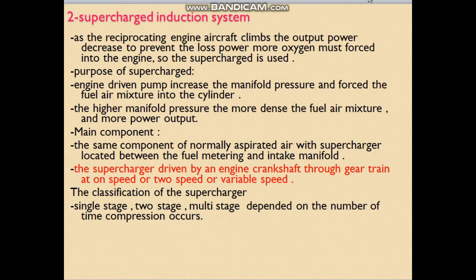What are the components of the supercharger? They are the same components as the normally aspirated system, with the supercharger located between the fuel metering and the intake manifold. The supercharger is driven by the engine crankshaft. You have to focus on this point, because when we study the turbocharger we will differentiate between the supercharger and the turbocharger.